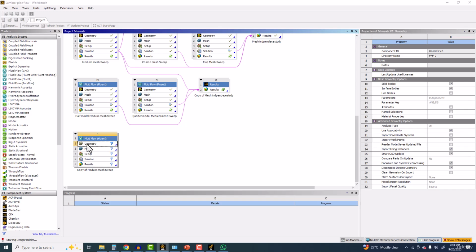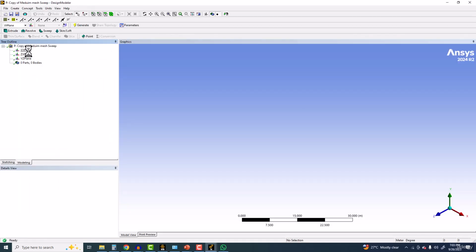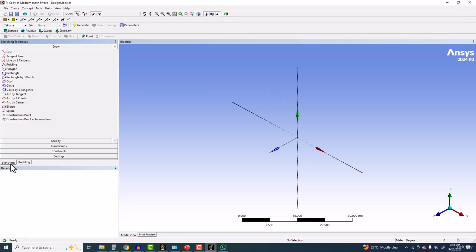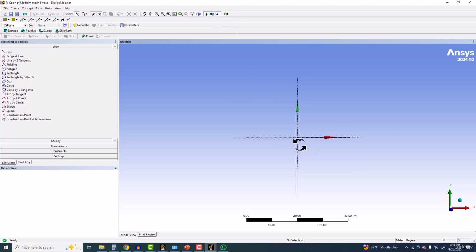We will not use the 3D features, only one sketch, and that is just a rectangle. The geometry should be made with one axis along the x-axis and the second axis along the y-axis. The z-axis should be 0, which means you cannot even translate the plane. Also, you cannot make geometry on the other side; it should be in the first quadrant.